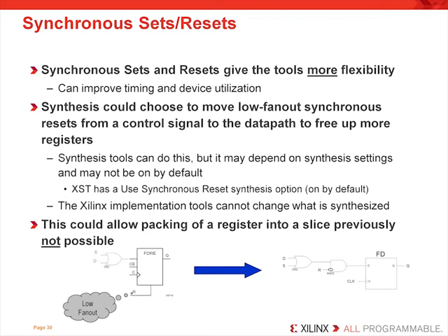As mentioned earlier, XST does have the ability to move a synchronous reset to a LUT input rather than connect it directly to the reset port of a register. However, if you don't use XST, your results will vary because not all synthesis tools can do this.